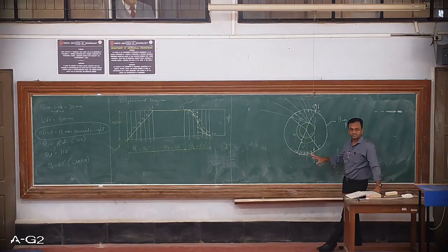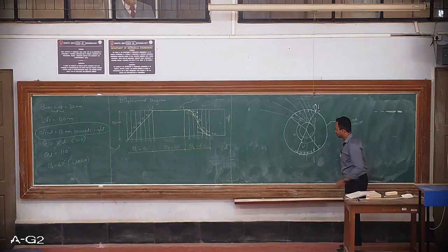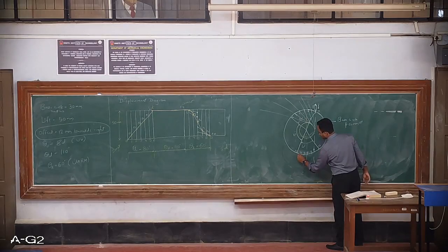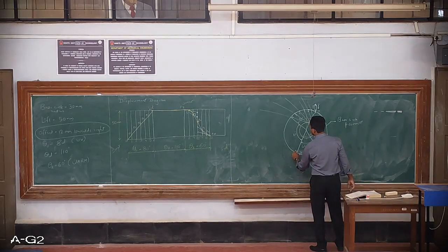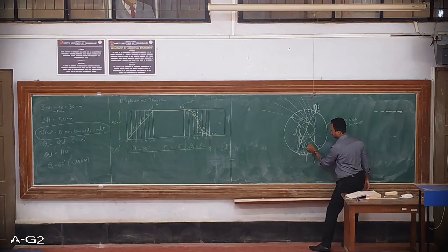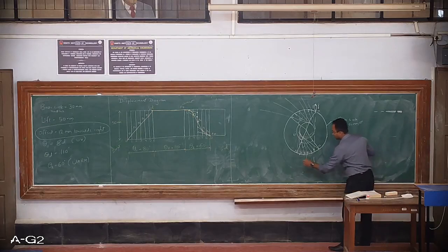Now look how I am going to draw the tangent from point 8 onwards. From point 8, do not draw the tangent line towards the right side. It has to be to the left side only. So I'll start with 7. From 7, I have drawn a tangent line. From 8, from 9, 10, 11, 12 and 13. So I'll extend these tangent lines.